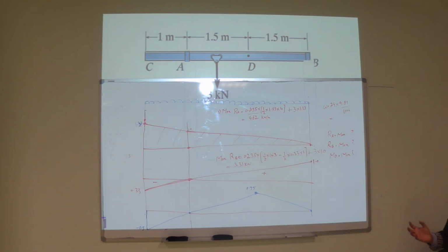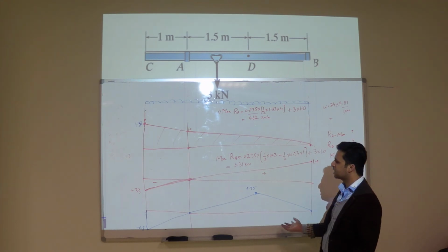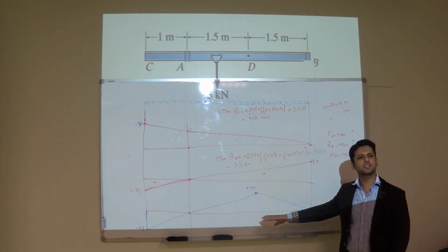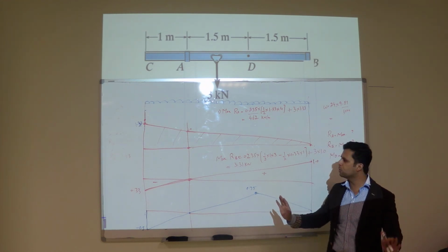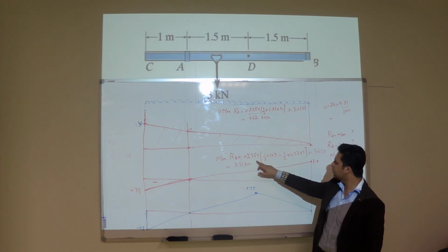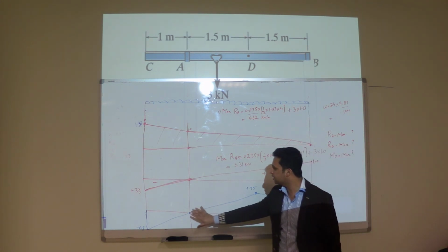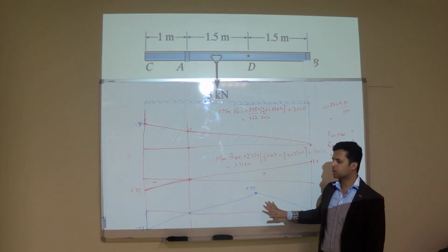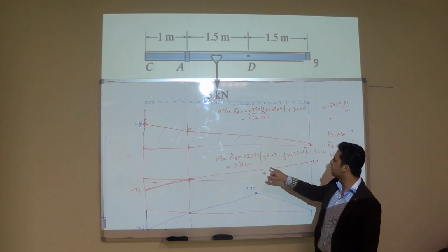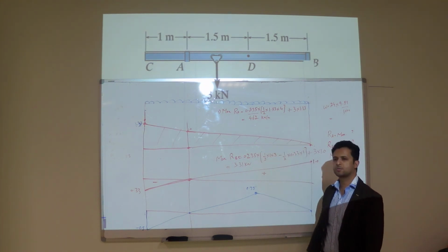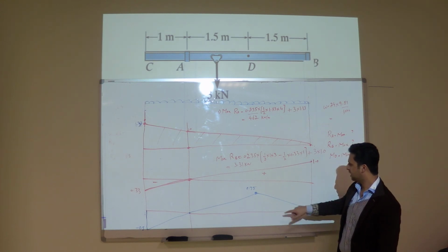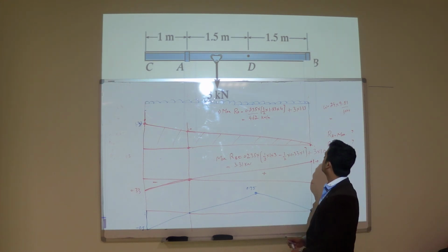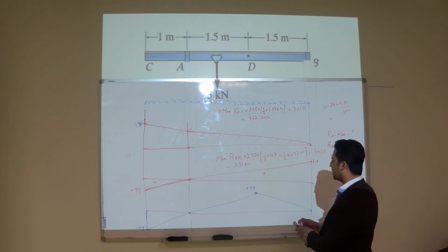The same way, when will you get the maximum moment? The UDL is present on the full length. So for the UDL, you will calculate this total area, plus minus negative. And when will you get the maximum moment due to the point load? When the load is here. Yes. Okay. So the moment at point D, I write it here, will be maximum.